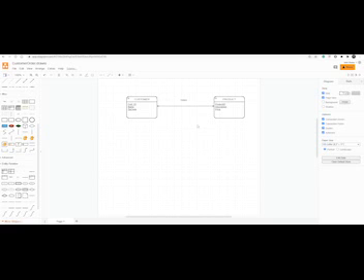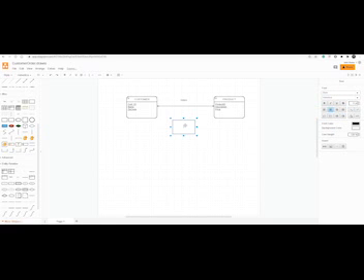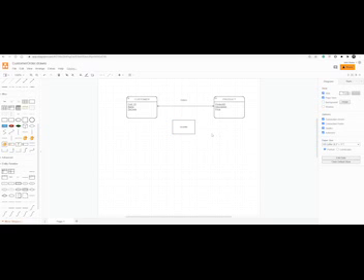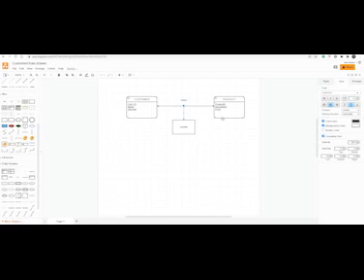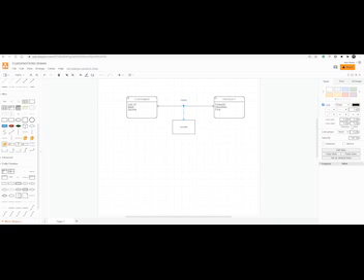And then finally, I want to have some attributes on this as well. So what I would do is maybe take another small square here, and maybe I want the quantity ordered. Okay. Now I need to put a line here, so I just click on my line again, wait for the little ball to show up, and put that across. Didn't like me that time. There we go. Okay. And this time I'm going to say none for these. So style none on each side of that, and I want it to be a dotted line. So right up here, I'll click on dotted, and that's it.